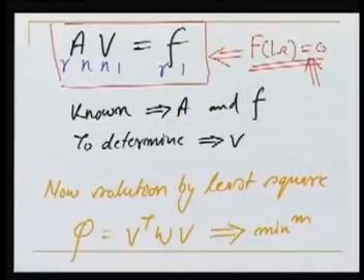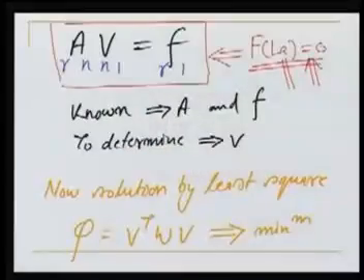Now once we are writing these equations using the conditions, LA here stands for the estimate or the adjusted observation. So once we are writing the equations that way, this is important here, we are writing the conditions in terms of estimates. That's why F(LA), this is important, is equal to 0. This is our starting point.